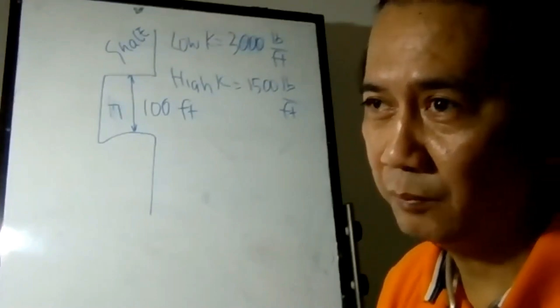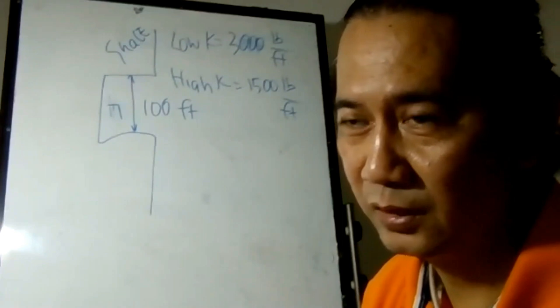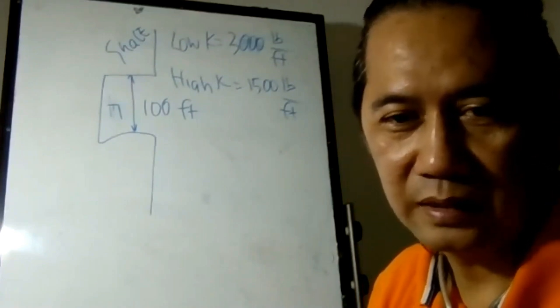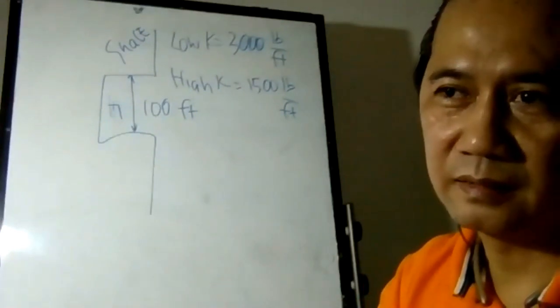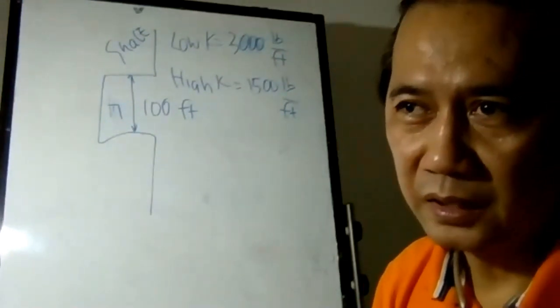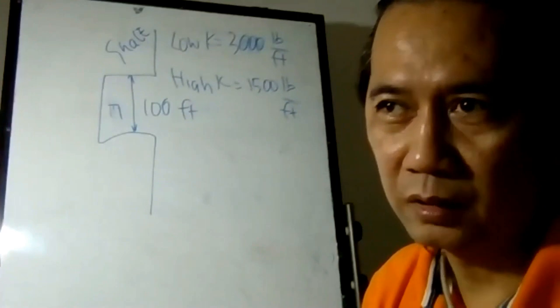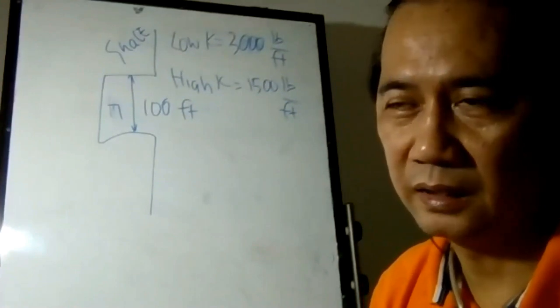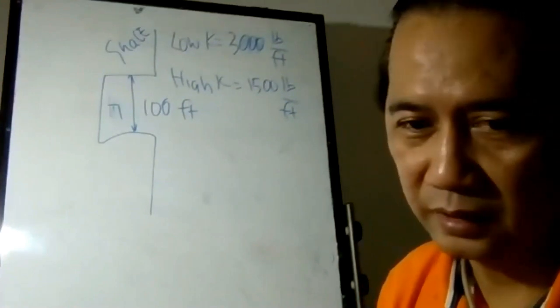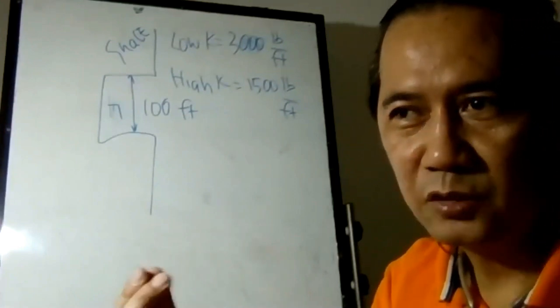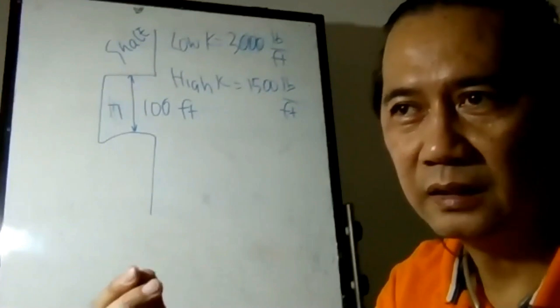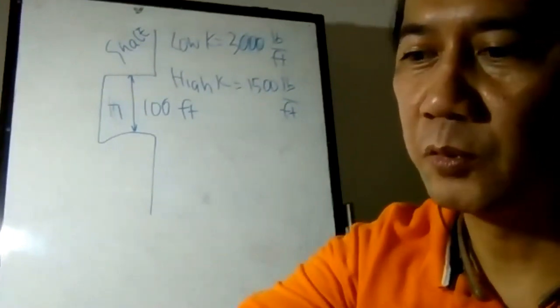If you remember what I said, I need the fluid viscosity to be able to carry the proppant, otherwise the proppant can drop and settle. The proppant companies, like Carbo or Saint-Gobain, or anything from Europe, US and China, developed what they call lightweight proppant. It can be half the weight of typical ceramic proppant.